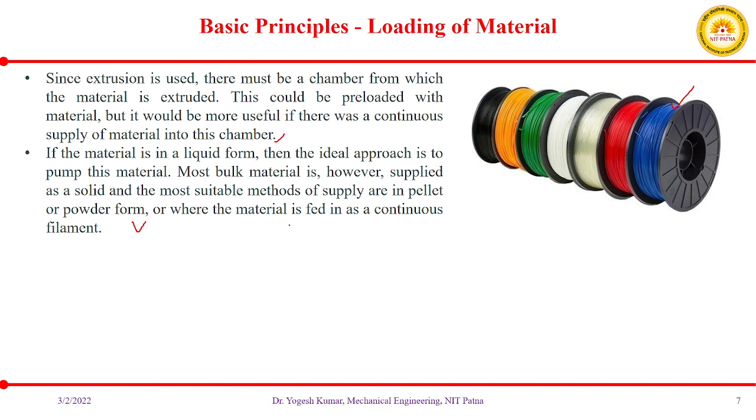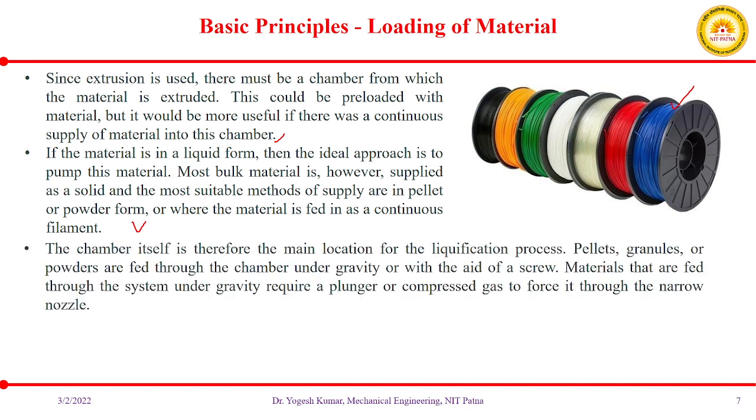Okay, so the chamber itself is therefore the main location for the liquefaction process. Yes, liquefaction takes place in the chamber. Pellets, granules, or powders are fed through the chamber under gravity or with the aid of a screw. Materials that are fed through the system under gravity require a plunger or compressed gas to force them through the narrow nozzle.